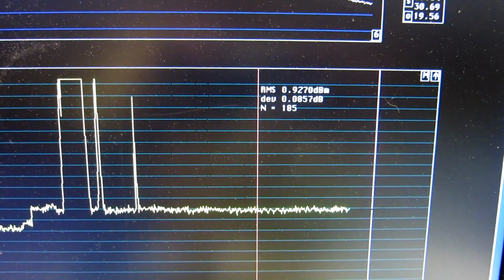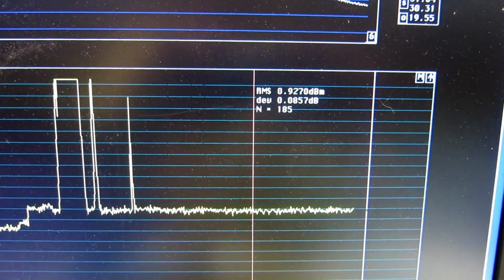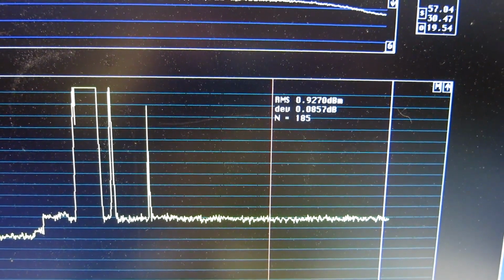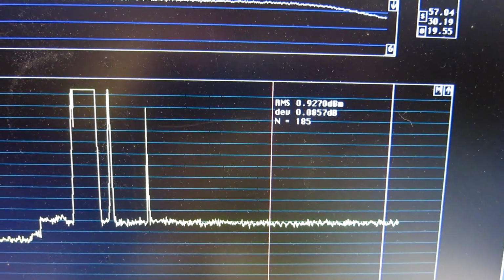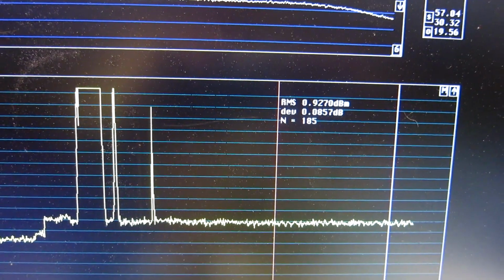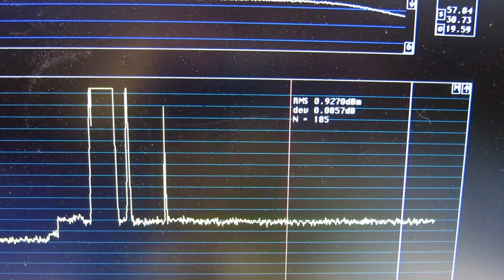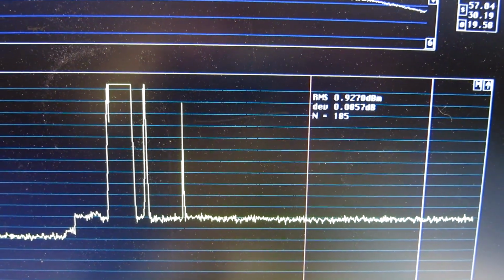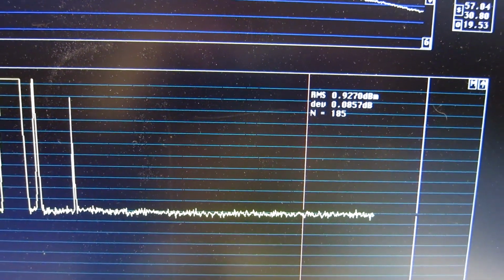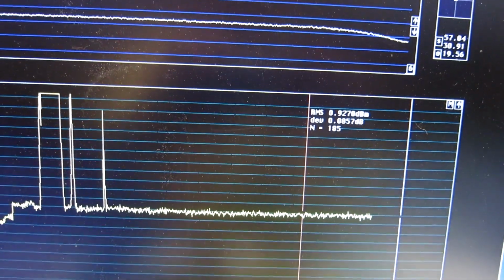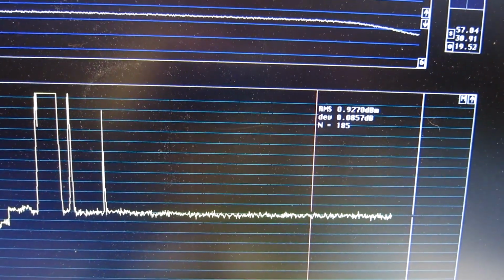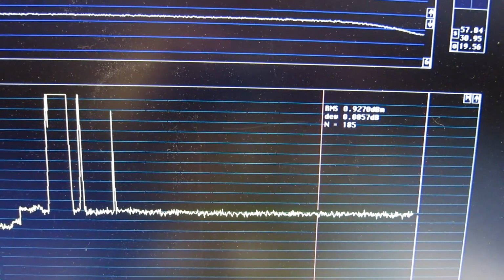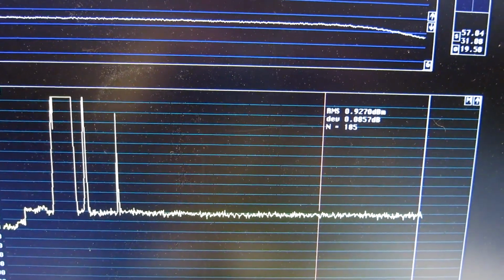The noise floor is much higher now. That's the noise from the bipolar transistors. If I could have a better final transistor, I could lose less current through these ones, and that would reduce the noise contribution from them. But I don't know much about low noise transistors. What I have in my junk box is everything more than 20 years old.